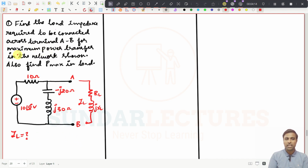This is the maximum power, right? So to transfer maximum power, what should be the ZL? ZL should be ZTH star, or you can write it as RTH minus JXTH. Right? Can you understand? So this is the thing you need to find.